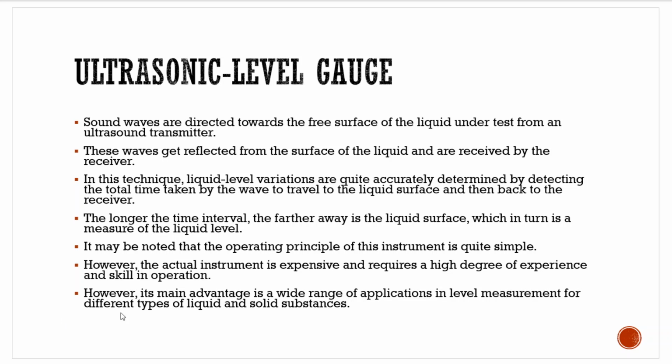We have the ultrasonic level gauges. They are again used for measurement of levels. Sound waves are directed towards the free surface of the liquid whose level we need to measure. In this case, we have a transmitter that will be generating ultrasonic waves. This device can be installed on top of the